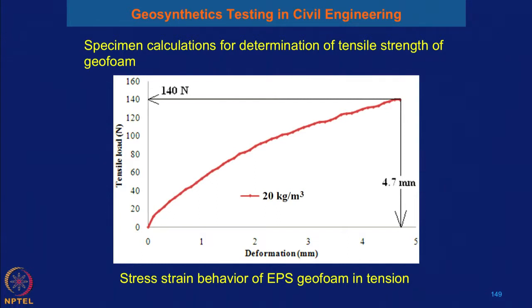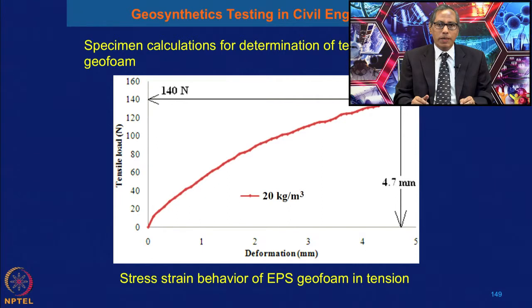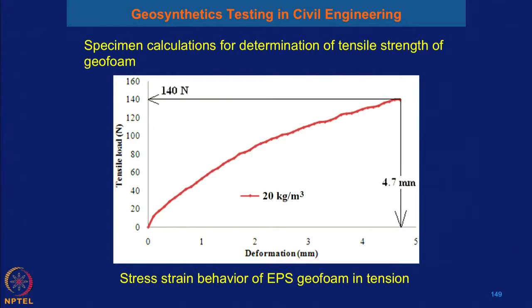So, this material not only gives the compressive stress of the EPS geofoam material, but also provides us the tensile strength of the EPS geofoam material. And for a defined strain value, you can also determine the tensile strength of the EPS geofoam material.